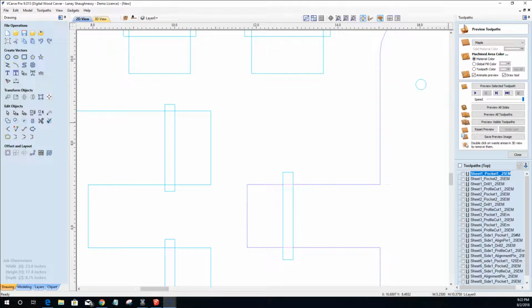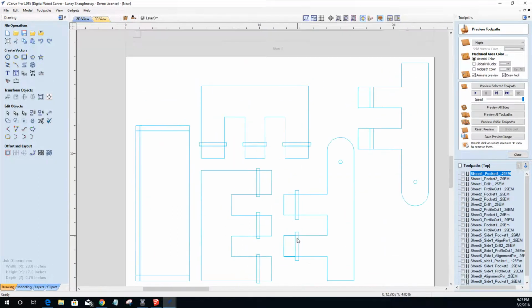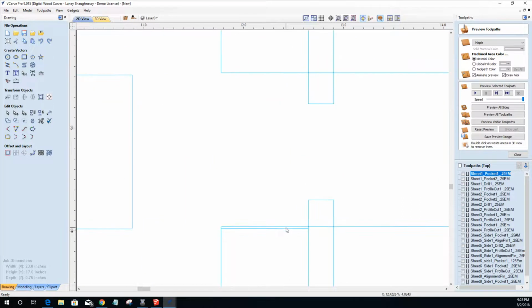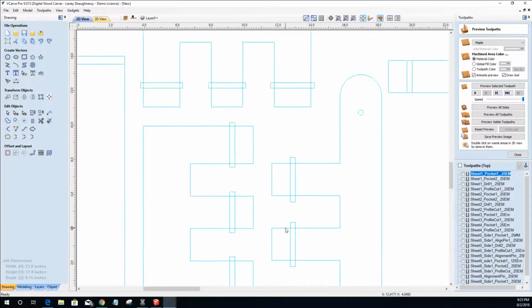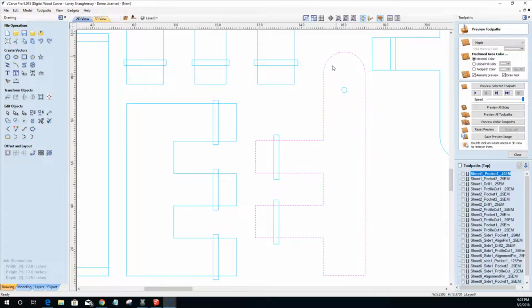She gets excited. All right, so if I'm very, very careful, if I just use my up arrow key on my keyboard one time, move it up, all that does is get it off those two vectors, and I can go through and hit delete, delete, delete, and then I should end up with my profile cut.